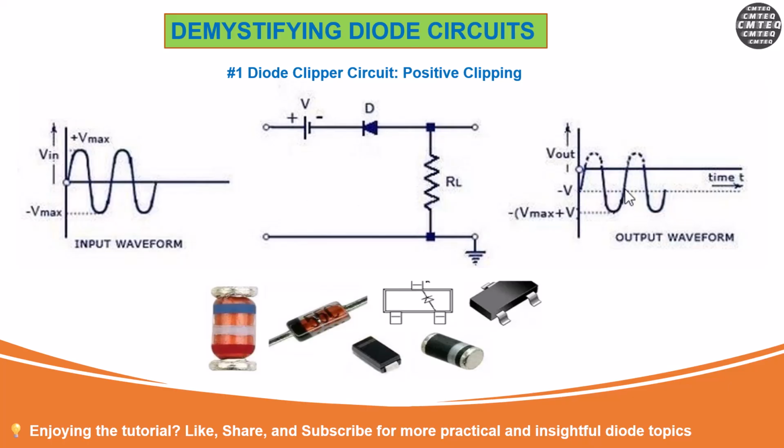And this cycle will continue again, starting to rise, and as this voltage becomes again bigger than this voltage, the diode will be forward biased, and we're going to get that excess voltage clipped, and the cycle will continue on the negative cycle. The output will follow the input.